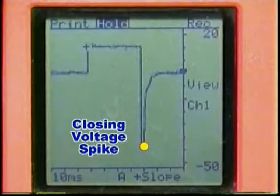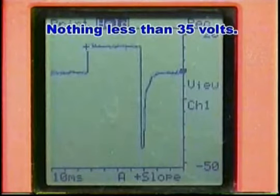The spike, following the injector shutdown vertical line, is clipped by the internal circuitry of the ECM. By studying this spike, we can know if there are shorted injector coil windings within the injector itself. This spike is generated by the self-induced voltage of the collapsing magnetic field around the injector coil. You should not have anything less than 35 volts. This spike is never clipped below 35 volts. In actuality, this measurement is a sign of the general health of the injector coil.